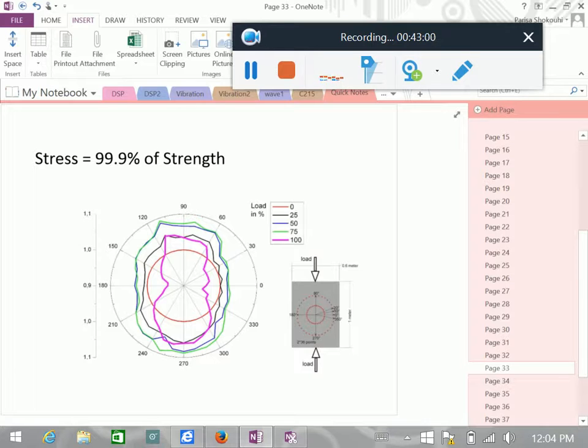Exactly. If it is under stress, you should measure a different velocity than when it is not under stress. So that's one. Another thing is just to be conscious that stress also changes the velocity. You saw that the change that you measure in velocity because of damage is not that much. So if you have a building, or a bridge, or anything that you are measuring, mapping the velocity over, some of these changes may be just because of the confining pressure that you are applying on your material. In rocks, this is kind of a well-known thing.